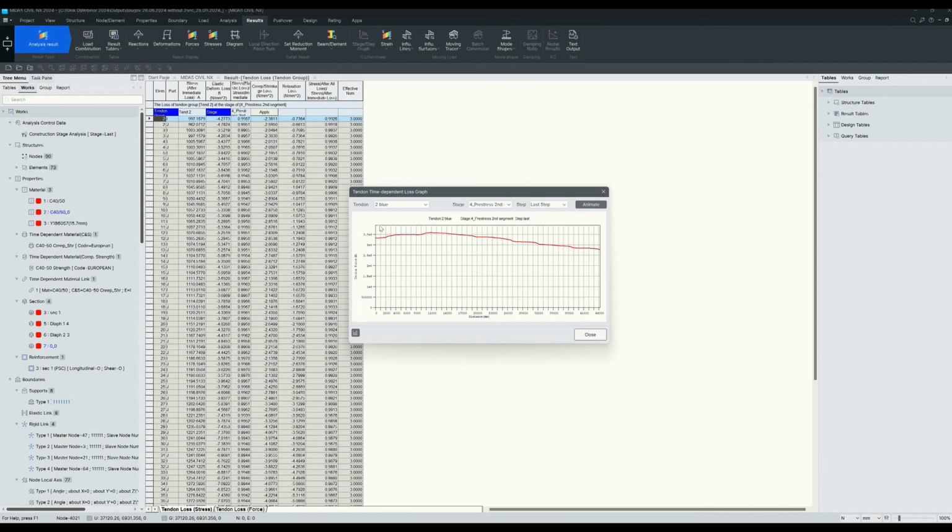In addition, it can be seen that there is a short section on the active anchor, at the beginning of the graph, where losses drop dramatically due to anchorage seating. To avoid mistakes, here you can easily check whether you chose the right position of tendon to jack in your model. Also, there is a queued function. You can ask to animate tendon loss over the life of the deck.